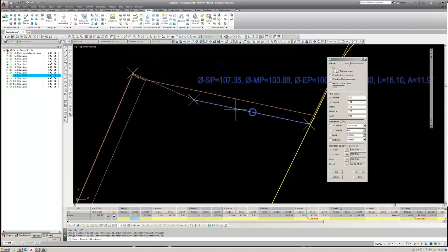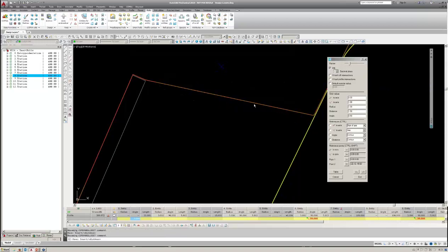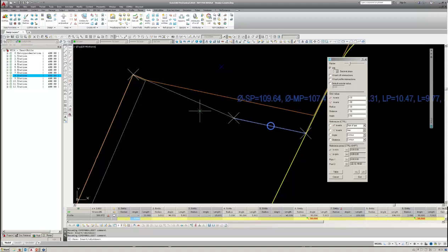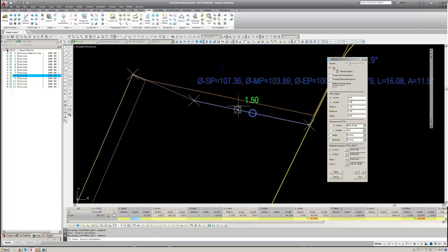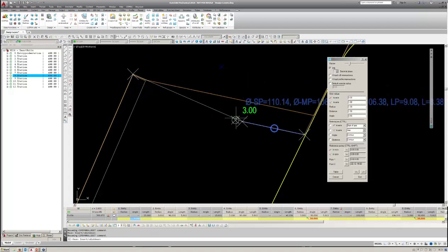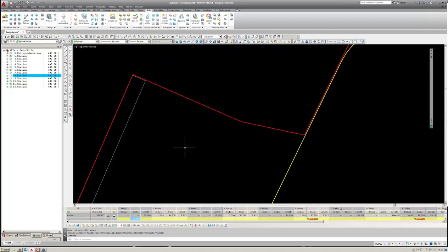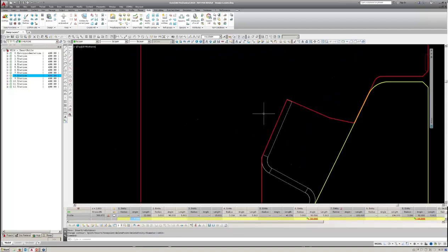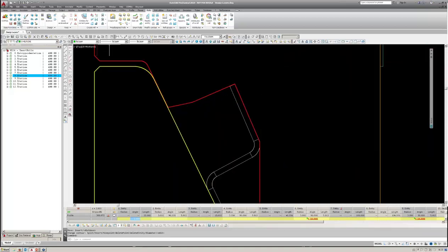So formally we'd have to construct this, okay? So again, my distance is defined to 1.5. So if I do the Control and Windows key, you can see now I'm snapping in 1.5mm increments here. And right click and it's done. And of course now, because it's a clone roll, the same has happened to the roll over on the other side as well. So I think normally this would take a lot more time to construct.